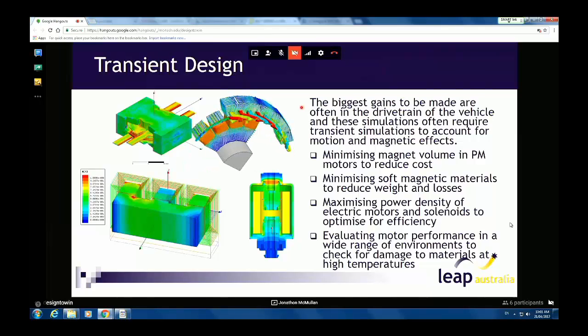So by coupling Maxwell with ANSYS Mechanical, you can do a lot of these verification activities fully automatically within Workbench, including things like vibration. That way you know whether you can sacrifice some mounting hardware to save a bit more weight.